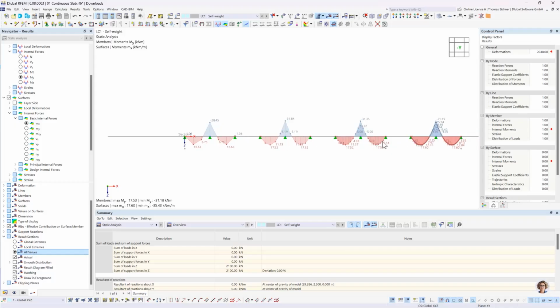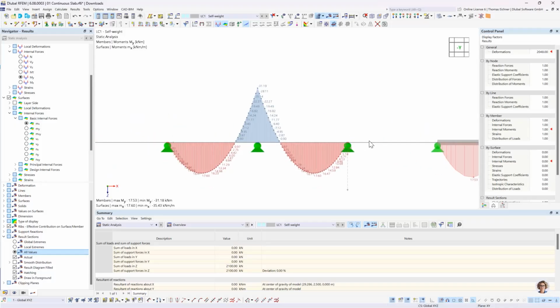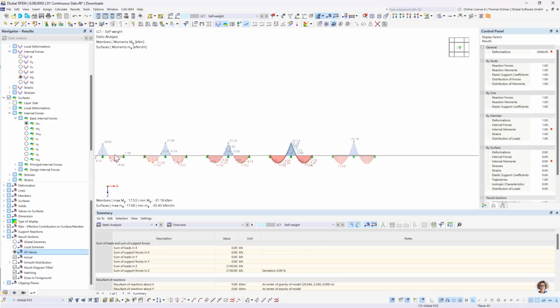But on the other hand, if you look at this one, it looks more like 100 elements, and this means also 100 kind of degrees of freedom here between each element. That means the solver and the calculation system is way bigger than in this first case. For this simple structure, it doesn't really make any difference since it's fast anyway.